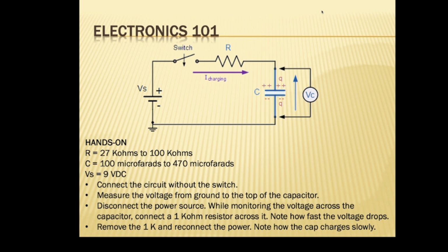846 seconds, because it was coming up very slowly. If I divide that by 60, that gives me about 14 minutes to actually charge it up. Now, if we put in a smaller resistor, that time would come way down. Or if we used a much larger value capacitor like this one, the time would go way up again.